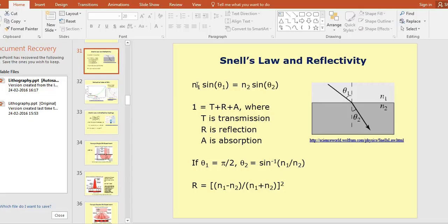Immersion lithography is the modified form of optical lithography to get better resolution for miniaturized devices, where we can have better resolution with more accuracy. It is done inside water, because the refractive index of water is higher than that of air, and a higher refractive index gives you better resolution, or smaller pattern features that you can fabricate using the same system.